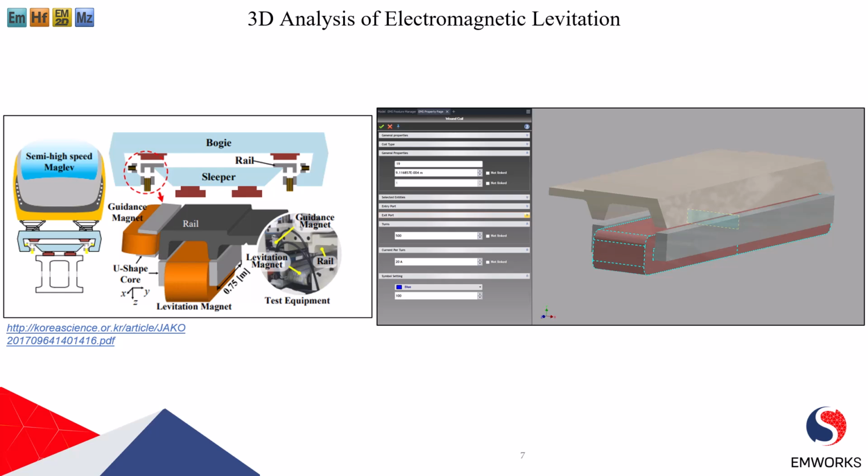This one is a section of your magnetic levitation system. It represents a planar symmetry. In case of a 2D simulation, we can just simulate a section of this system to save time and increase the design iterations. The levitation magnets are used to lift the train. The bottom electromagnet and the left and right side magnets are added to maintain certain alignments of the system.